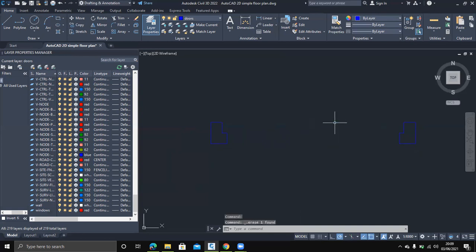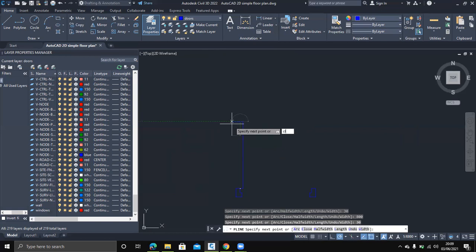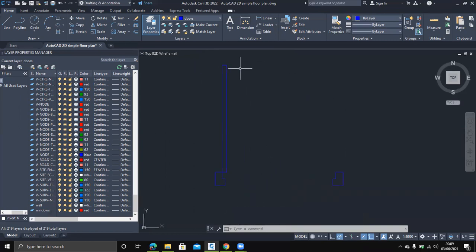and that line was just supposed to help me do that, so I will just delete it. And then once I'm done, let me just draw the polygon that is from this corner here, some 30 units, and then also some 800 units, and then there's also some 30 units this way, and then I will type CL to close that polygon. So you can see now our door is taking some bit of shape. So this blue is a bit faint, but I believe you guys are able to see when I move my mouse to the respective positions.